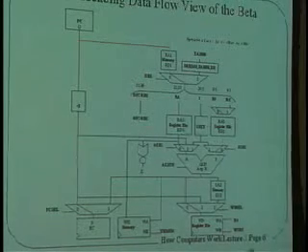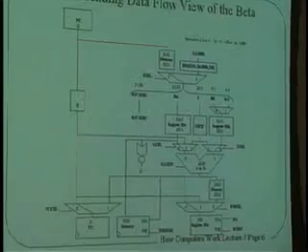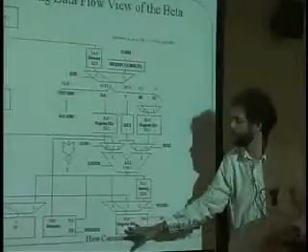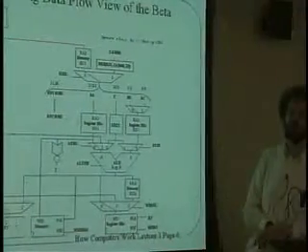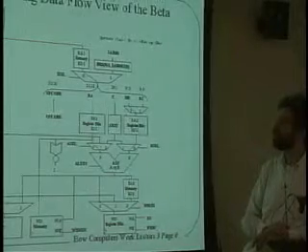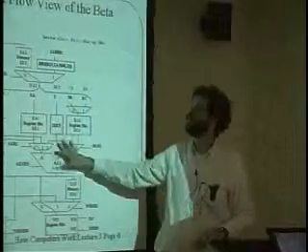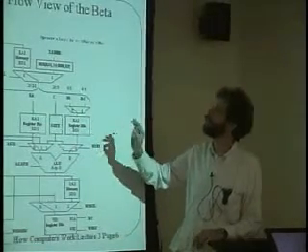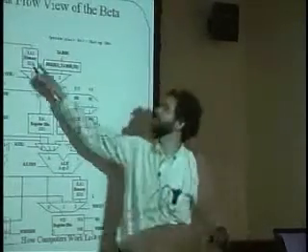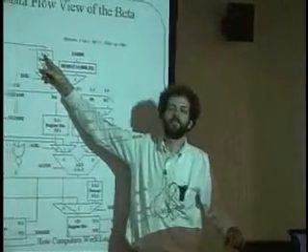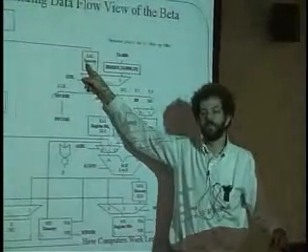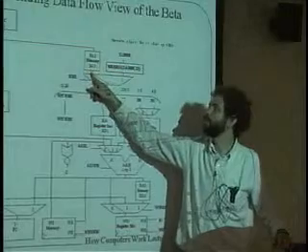Is it generally one clock cycle per movement opcode down there? Yes. So the data moves through all of this stuff, and then the clock goes off. Oh, that whole thing is one clock cycle? Yes. There is nothing here that holds up the data. If you remember, the model of the memory is that as soon as an address comes in here, it figures out what's at the location that the address points to and the data comes out.